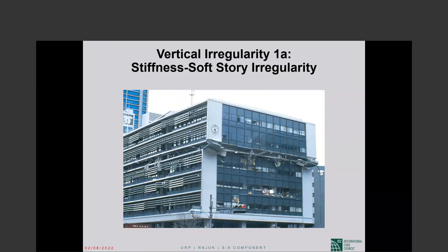After the war, everything was scarce, and the Japanese built structural steel shapes into concrete, which were discontinued at some point along the height of the building because steel is expensive, and they felt that they did not need all the stiffness up there, where the displacements expected were not large.